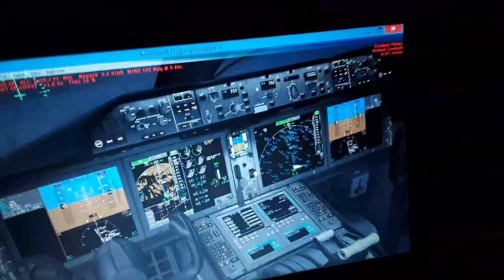So we have the GEnx turbofan engines installed in our Boeing 787 jet aircraft, one left wing, one right wing. Each engine produces a lot of thrust and contains a gearbox with the FADEC. The FADEC is the full authority digital electronic control computer. There are two for redundancy. When one fails, the other takes over, and controls most of the displays of the engine data.